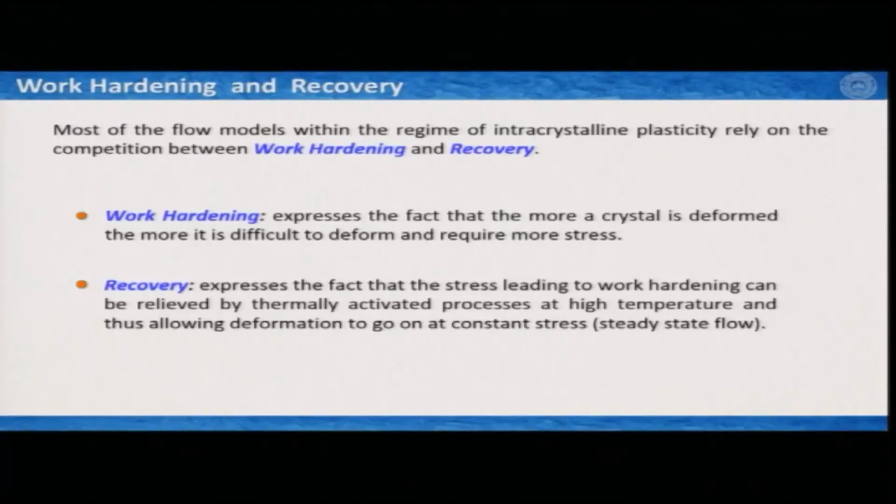Now, what is work hardening? Work hardening expresses the fact that the more a crystal is deformed, the more difficult it is to deform, and it requires more stress. That means the system that I am deforming through the mechanism of intracrystalline plasticity requires more and more stress to deform it.